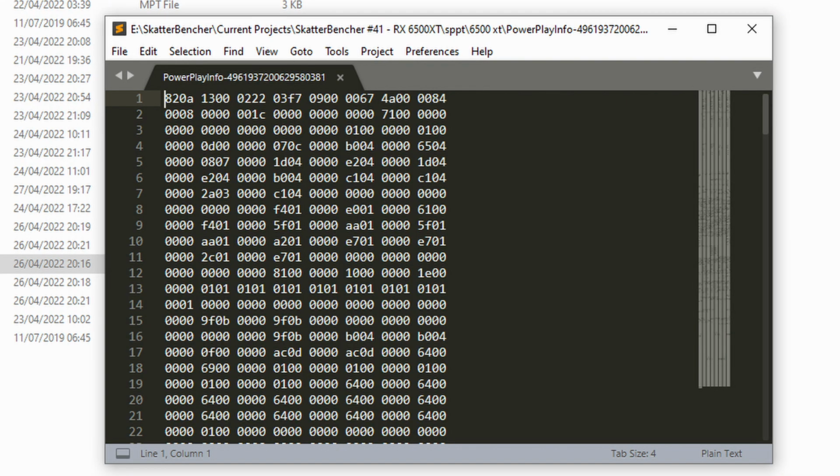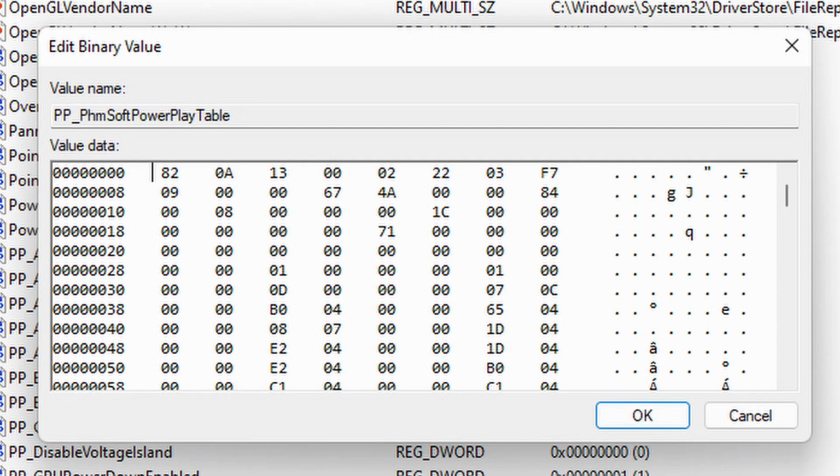The graphics software has a PowerPlay driver component that reads the information from the VBIOS and configures the appropriate frequency, voltage, and fan speed configuration. End users could override the PowerPlay driver configuration using a soft PowerPlay registry entry. This registry entry is essentially a direct copy of the VBIOS module. We'll touch on this topic a couple of times as it's particularly relevant for overclocking.